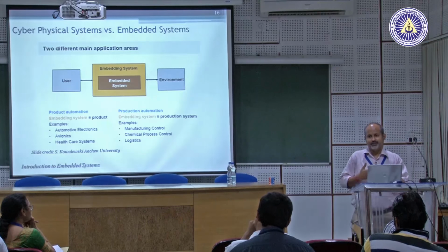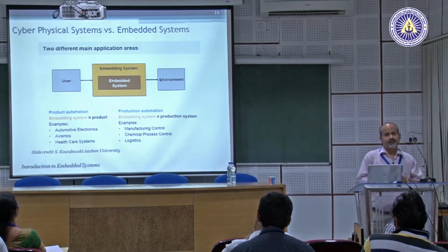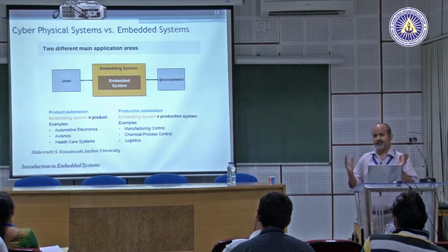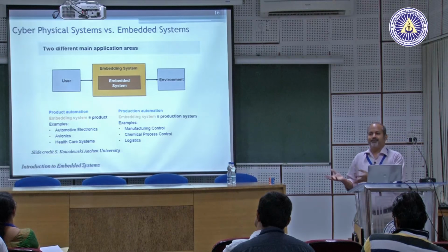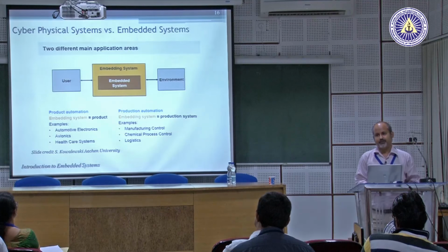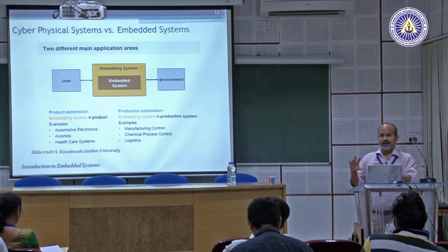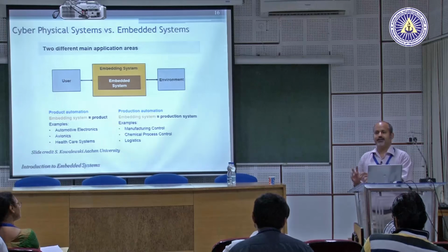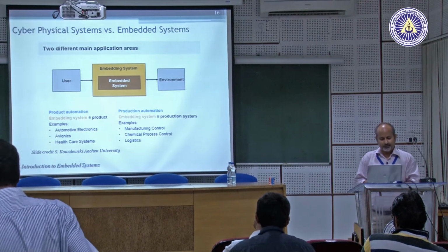Eventually in a smart grid, you would like all of these things to be done automatically in a closed loop, but right now we don't do that. But this is a physical system that is being controlled by a computational system, and this computational system is also distributed. So there are local controllers in a power system, as well as these control center specific controllers, and these controllers keep the system under control.